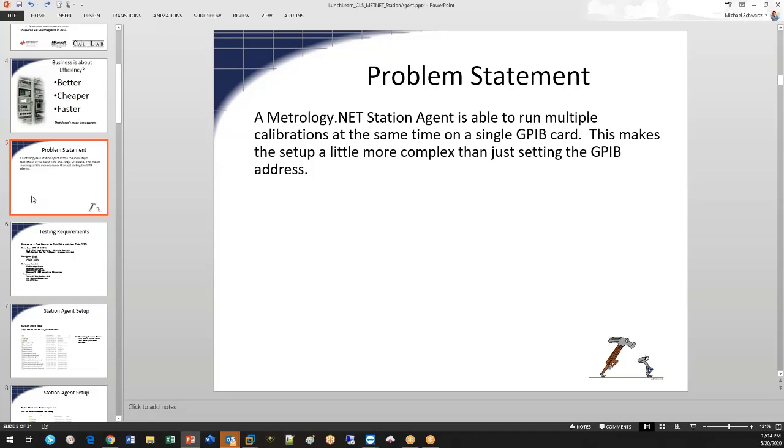One thing to point out is, as we're moving away from GPIB into TCP/IP communications, one of the limitations we have is how many GPIB instruments we can connect to a workstation. But as we're moving out of the GPIB world into LAN communications, there's no limit to the amount of LAN instruments we can have connected. So we can start seeing more work being done on our workstations as we do our LAN configurations as opposed to GPIB.